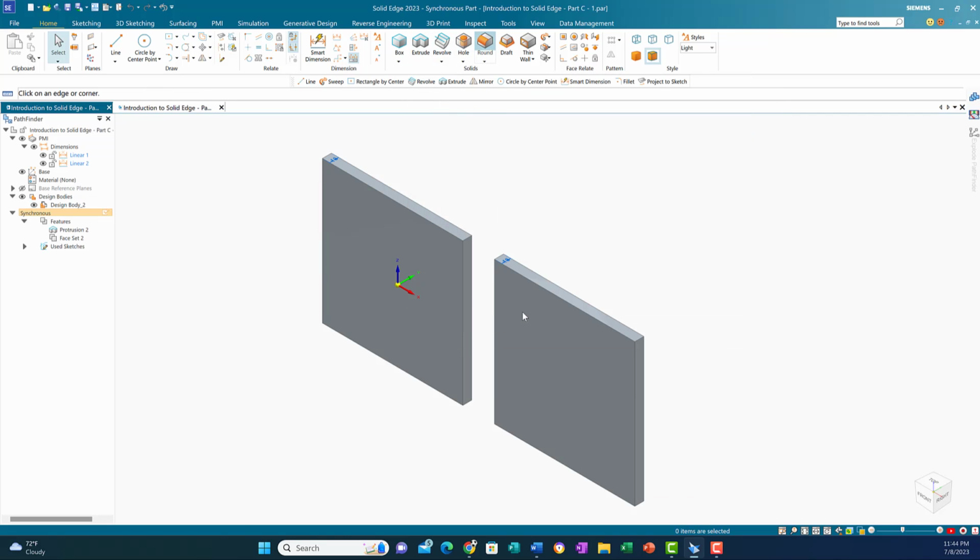I click on the round, get the edge here, and I need 50. That's fine. And click on the edge here, 50. That's fine. Okay. Let me move the other one too, and the other one here. When you see the line, you click on the line.